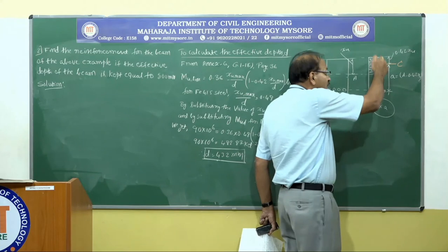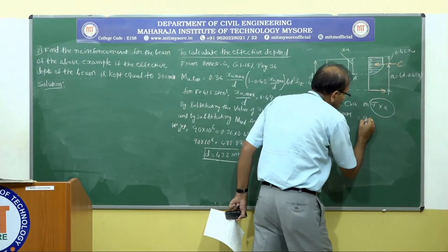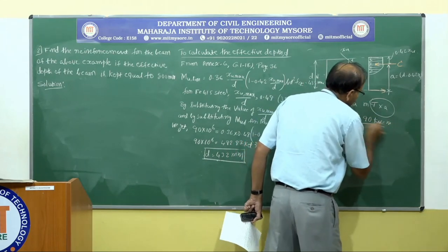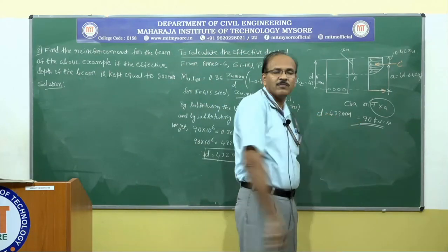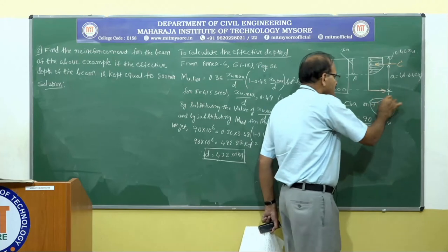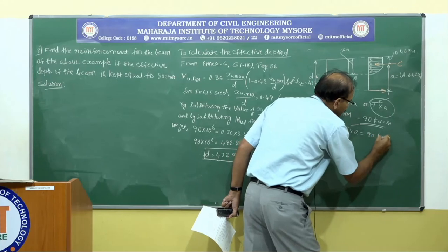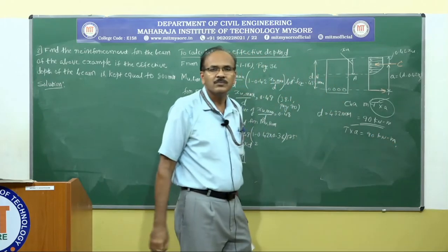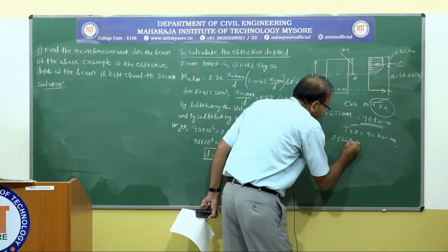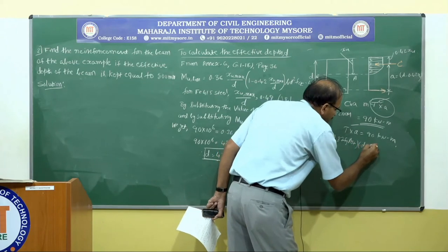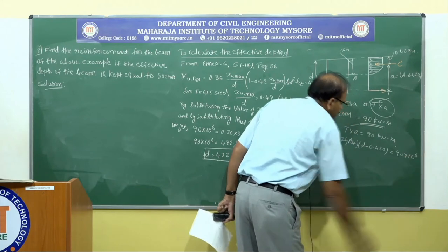So, what if we increase this moment? Okay, this moment is good enough to take care of this external moment to the load. So, this T multiplied by A equal to 90 kilonewton meter. Okay. So, this is say 0.87 Fy AST, and the lever arm is D minus 0.42 Xu, equal to 90 multiplied by 10 to the power of 6.